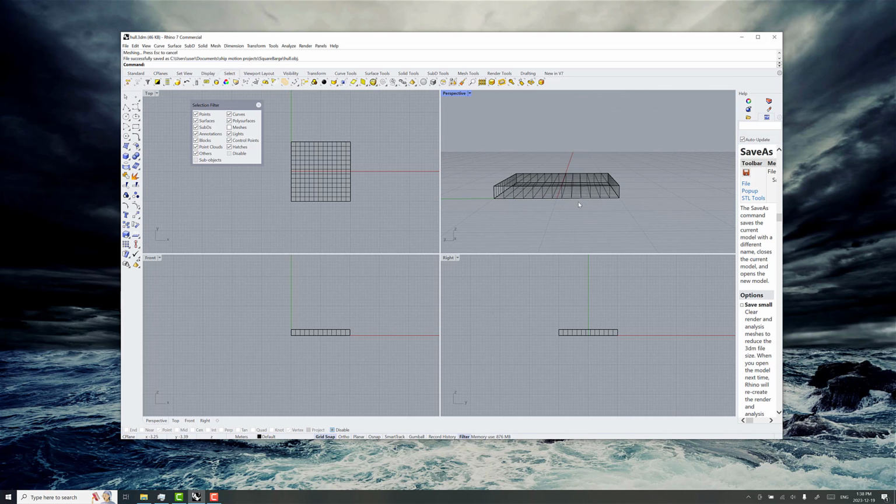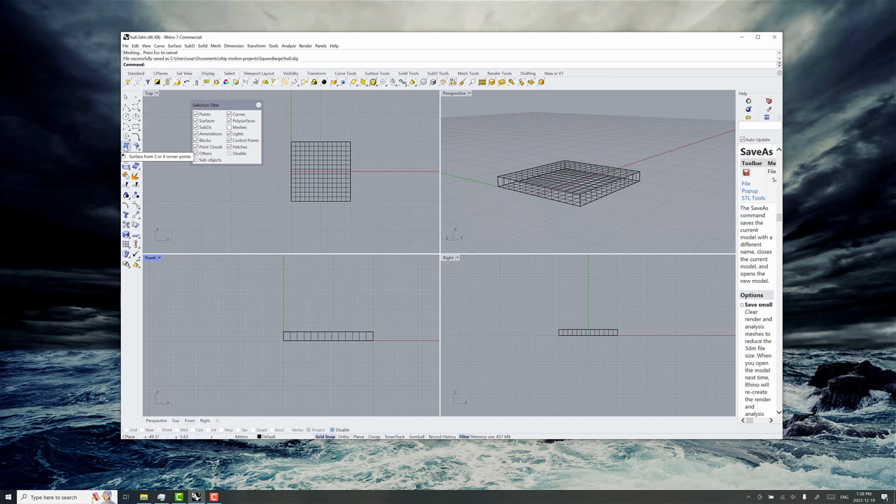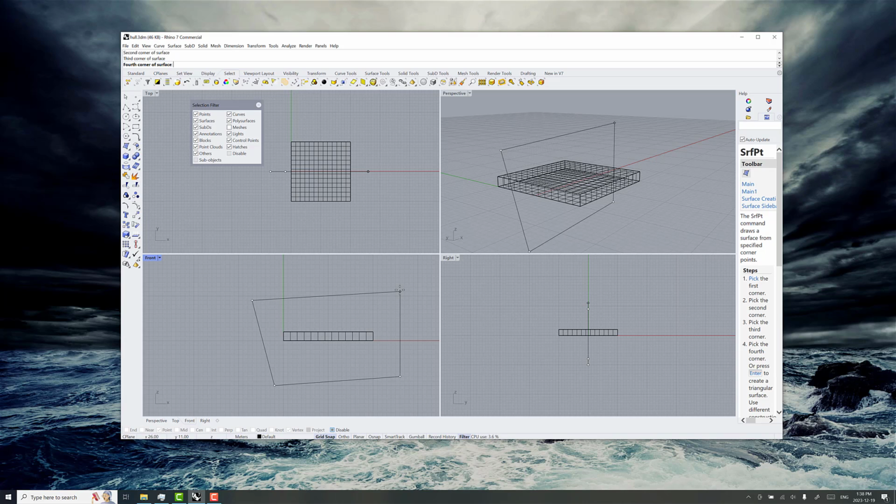Okay, now the other expectation that the Rhino3D toolset has is you're only providing in half of the hull, and it'll automatically get mirrored within the hydrodynamic process itself. So we can cut this in half pretty easily. We'll just pick a surface here, and then in the ZX view here, just pick some points. As long as it encompasses the entire section here, we're good.